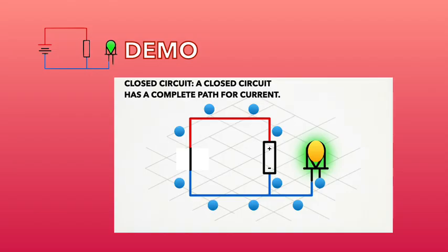The current flows from the positive terminal of the battery, through the connecting wires, and into the light source, LED or bulb. If it is an LED, the electricity must go through in the correct direction, positive (anode) to negative (cathode). Often a resistor is included in the path to limit current and protect the light from damage. After passing through the light, the electricity continues through the wires and returns to the negative terminal of the battery,